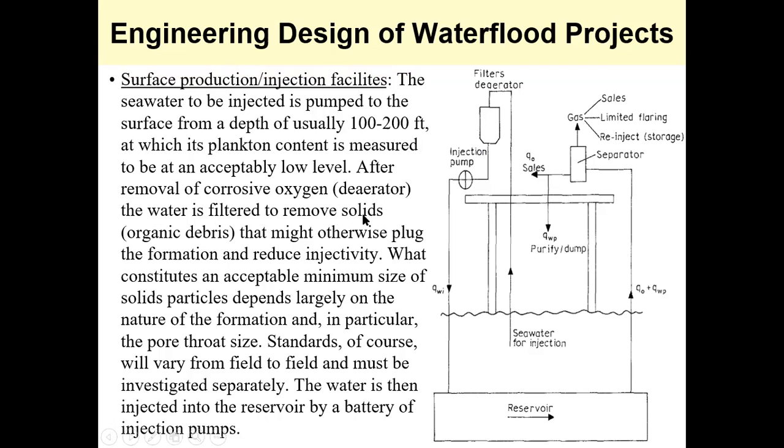And then the water is filtered to remove solids, which might otherwise plug the formation and reduce injectivity. What constitutes an acceptable minimum size of solid particles depends largely on the nature of the formation and the pore throat size. Standards, of course, will vary from field to field and must be investigated separately. Then the water is injected to the reservoir using a battery of pumps, and by the time it comes back to the surface, it goes into the separator for dumping of some of the water, reinjection, and